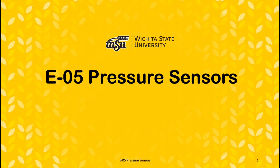Pressure is defined as the force per unit area that one material exerts on another. For example, consider a 10-pound cube resting on a table. If the area of each face of the cube is 4 square inches, then 10 pounds is distributed over an area of 4 square inches. So the cube exerts a pressure on the table of 2.5 pounds per square inch,